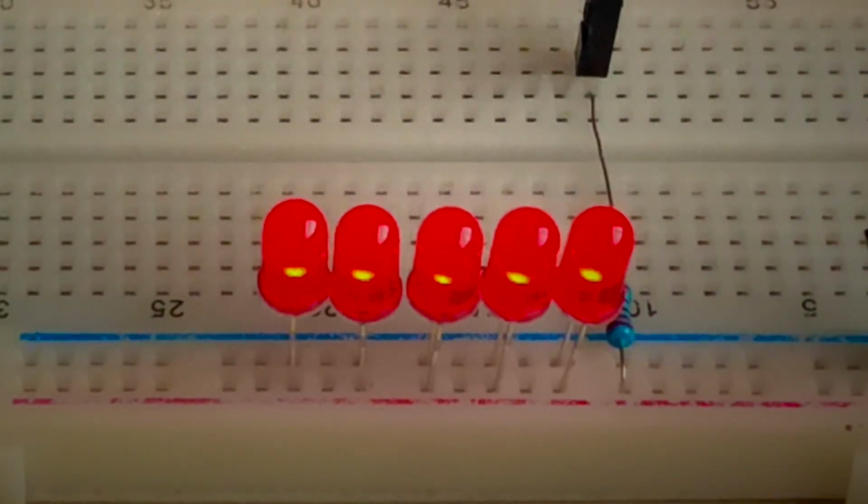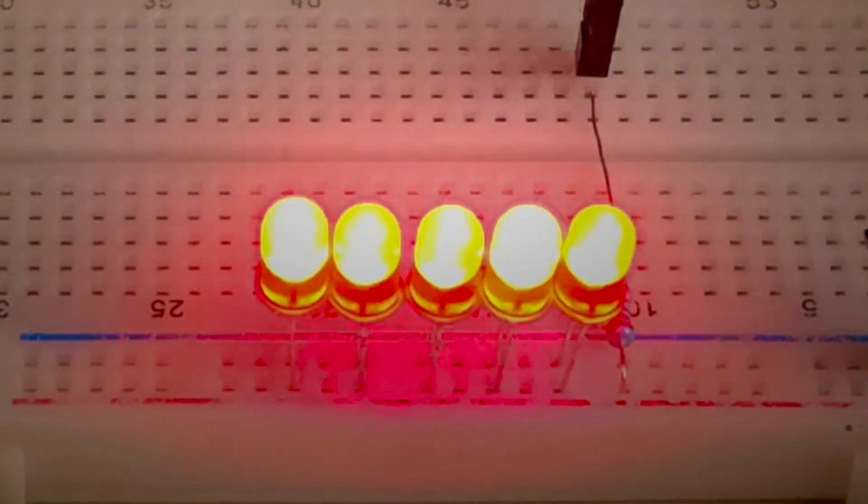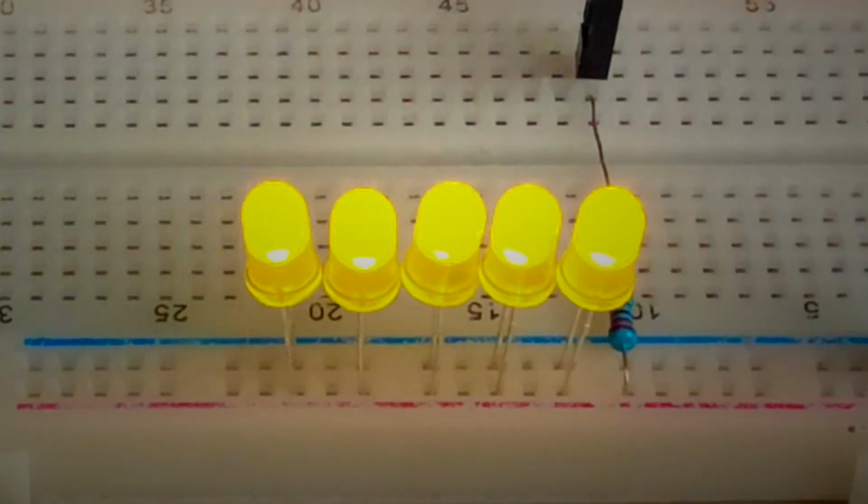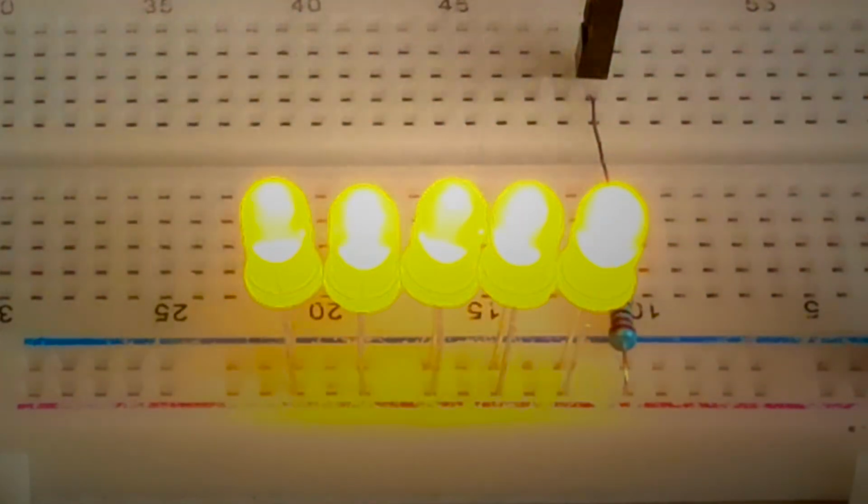Series resistors for each element are compensating for the negative temperature coefficient, and the current is evenly distributed across all transistors. However, the power efficiency is suffering from that. But there is also some really good news I didn't expect. At low power, parallel connection of LEDs is feasible.